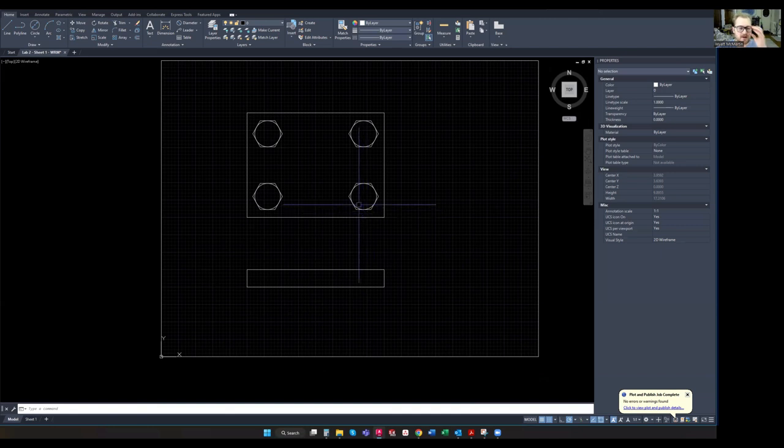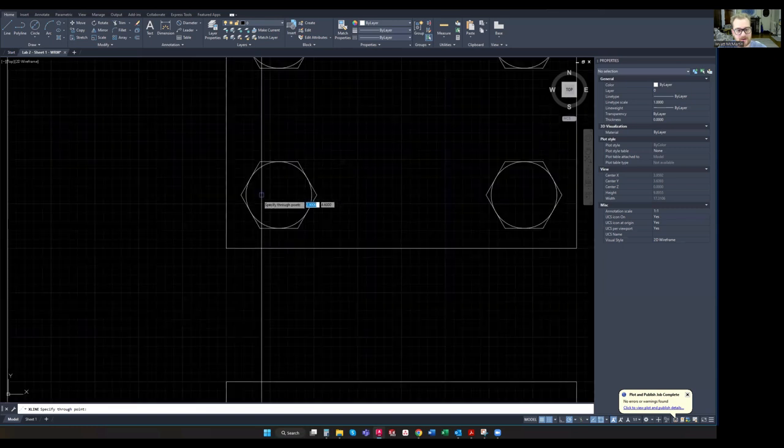So at this point, the easiest thing to do now is to create some construction lines, projection lines, that we're going to use to make sure that we're showing the location of all of these edges in the front view accurately. So we can drill in under the draw toolbar right here, and you can go ahead and grab your construction line. Alternatively, you can type XL enter, V for vertical, enter. And now we have a vertical line.